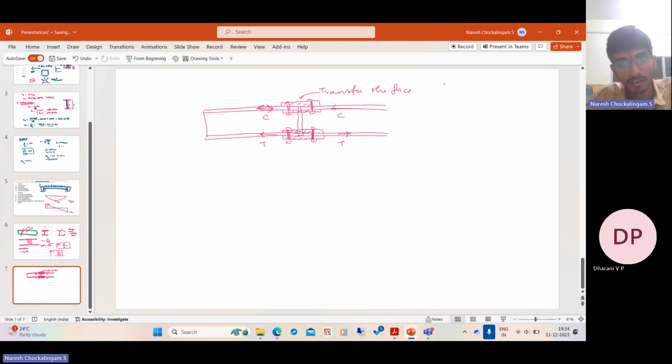But even in that case, the problem is, suppose you are bolting it. If you're bolting it, there's a clearance hole. The bolt will be something like this. There will be a small gap so that you can screw it in. There will be a clearance. The plate, yeah, this is fine.